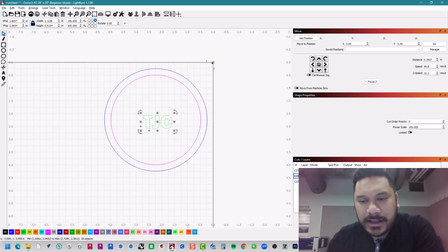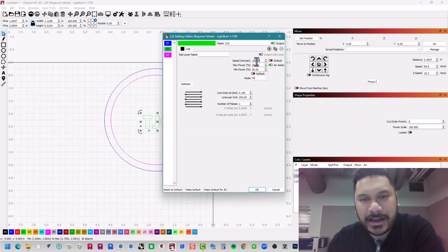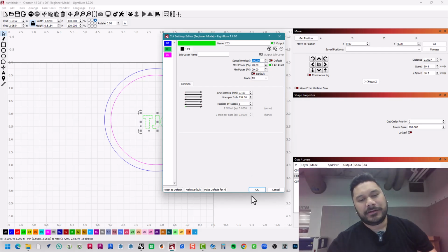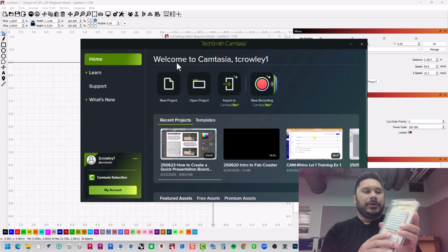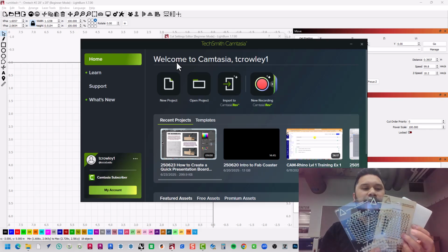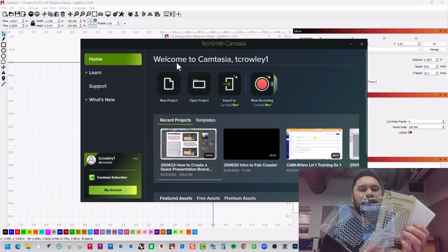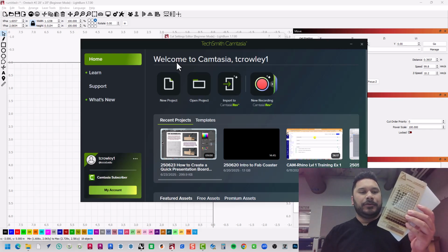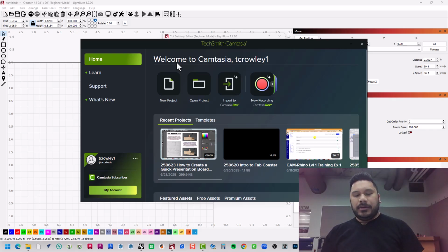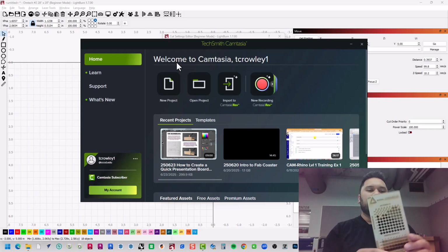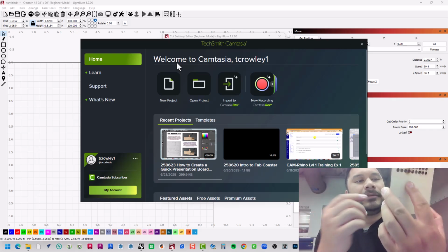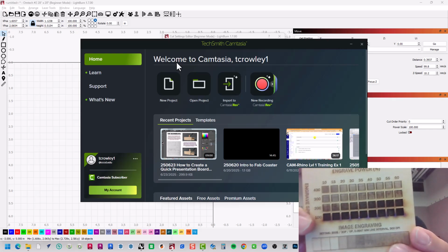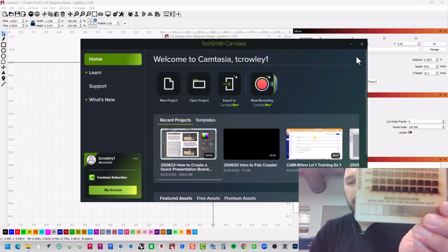And I'm going to take a look at some of the material test cards that I've printed over the last couple of months. If I'm making this coaster out of wood, I'm going to take a look at the wood material test card. So I'm going to put away all the acrylic ones, and now I'm going to look at this wood one. Looking at this wood one, I have cut settings and I have engraving settings. Looking at the engraving settings, I can find whatever one fits my style the best, right? This is my coaster, I'm designing it for myself.